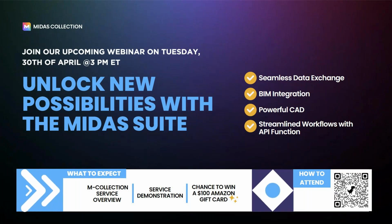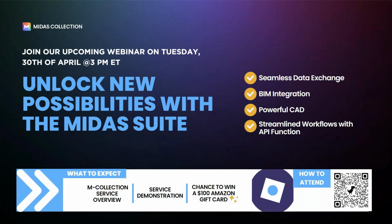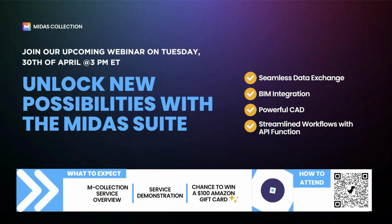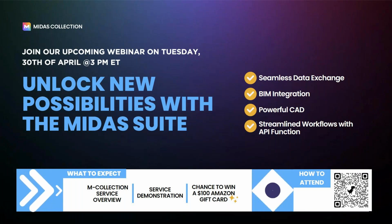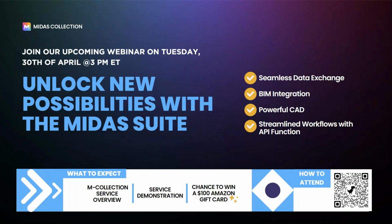Will Midas provide some libraries and instructions for implementing API into analysis and design tools? Yes, we will be giving some instructions in a documented form as well to get started with API. And we will showcase that in the webinar as well, where you can avail those things. Apart from that, we are also making some plugins. API is definitely a useful feature, but we are making some plugins at our end so that API is available for all the people. As of now, just to give you a highlight, we have a plugin based on the series load generator. It helps you perform a moving load analysis in the form of static load incremental analysis, where a set of static loads is run on a bridge. That is how plugins can be useful for you.